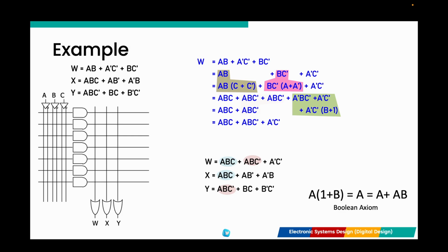However, PLA and PAL chips are limited to fairly modest size, typically supporting a combined number of inputs plus outputs of not more than 32 due to the limitation of the input and output size. Modern electronics applications require more inputs and outputs and functions. Hence, FPGA, the Field Programmable Gate Array, is introduced.